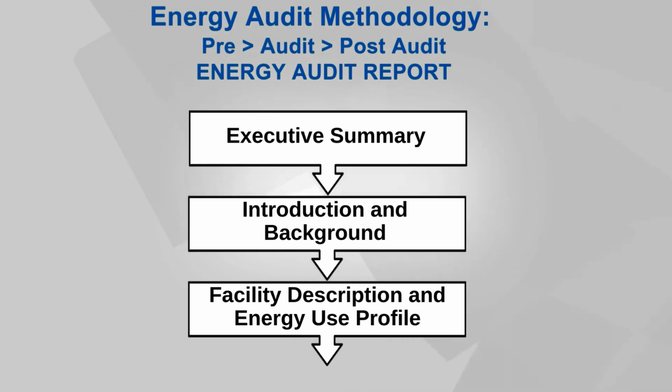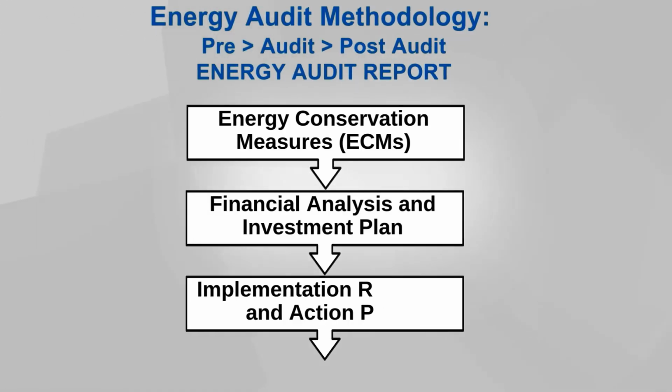The fourth one is monitoring and verification of energy savings. After the ECMs are implemented, a monitoring and verification, or we say M&V, process is established to measure and validate the actual energy savings achieved. The M&V plan defines the methods, metrics, and baseline conditions used to quantify the energy savings.